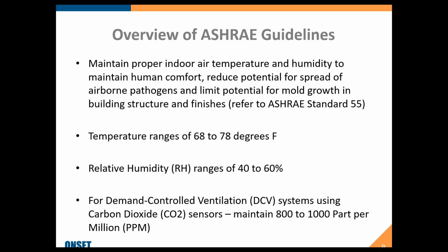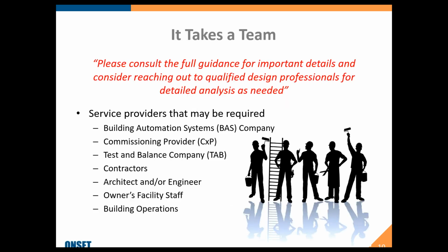If you're in Florida right now, you're probably not going to want to open up your windows and let in that 90% humidity, because you're just going to overwork the HVAC system. And for those HVAC systems using demand control ventilation with CO2 sensors, you're going to want to maintain 800 to 1,000 parts per million, or ppm. If you can hit the next slide.